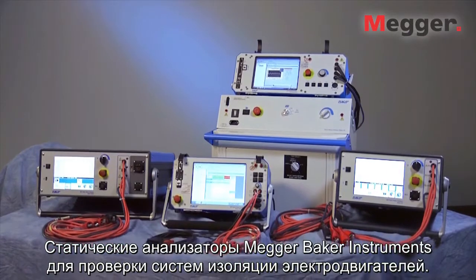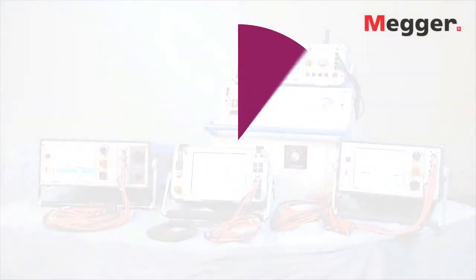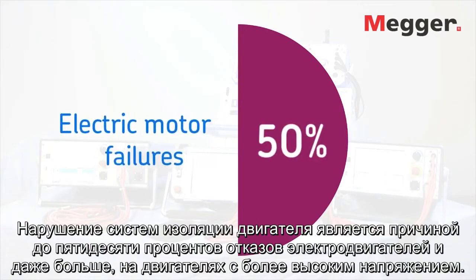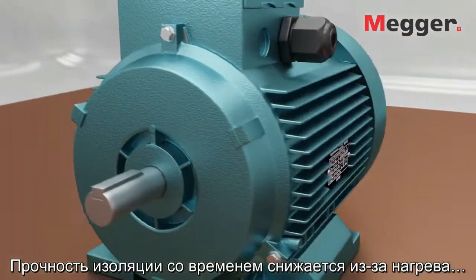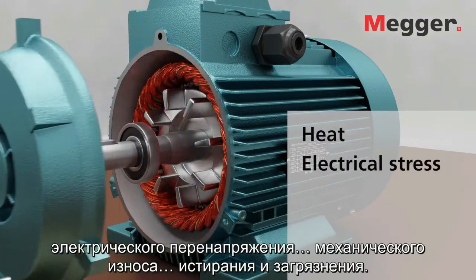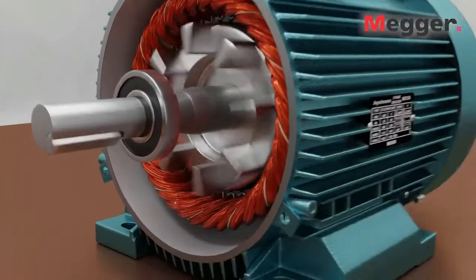Static motor analyzers test the insulation system of an electric motor. The motor insulation system is responsible for up to 50% of electric motor failures, even more on higher voltage motors. Let's take a quick look at the motor insulation system. Insulation strength degrades over time due to heat, electrical stress, mechanical stress, abrasion, and contamination.